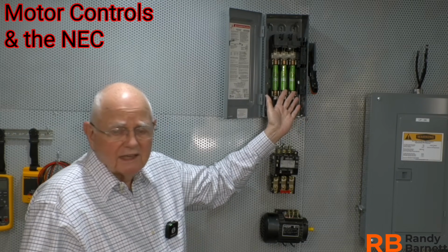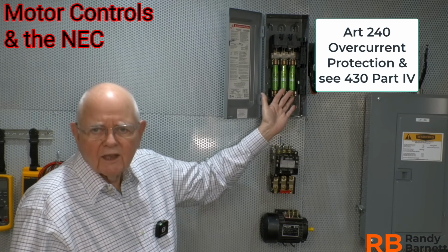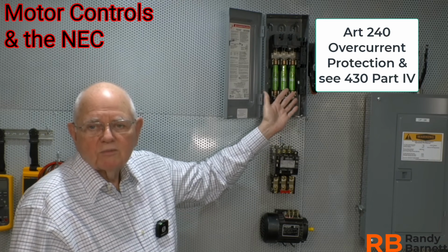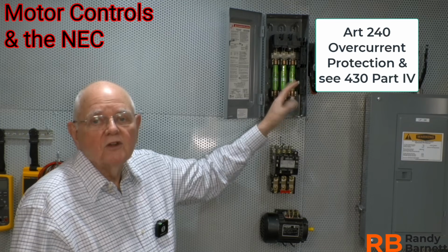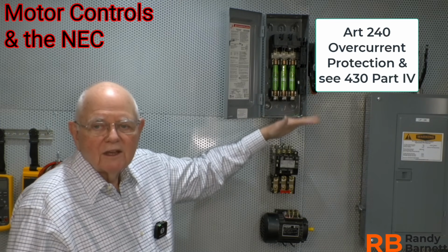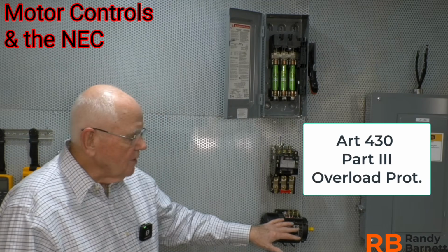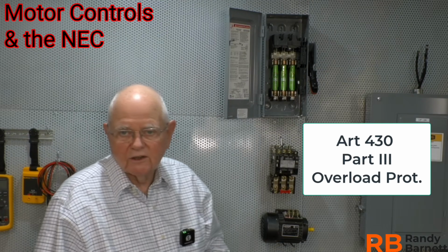I can take a look at that, and that's defined in Article 240, 240.4 is it? That talks about my overcurrent protection, short circuit, and ground faults. Fuses and circuit breakers are in place in order to protect the wiring, the conductors going down to my equipment. For protection of the motor itself, I have overloads that are going to do that.